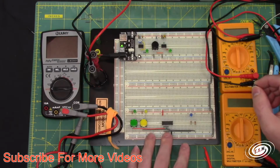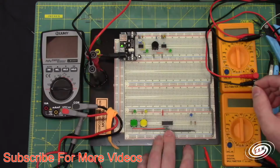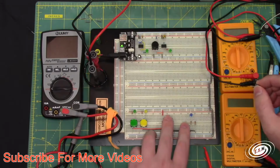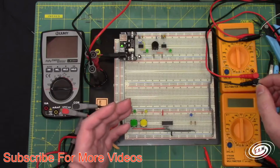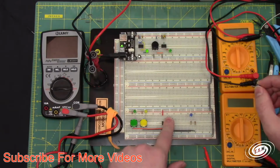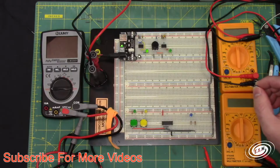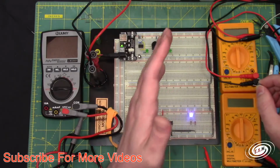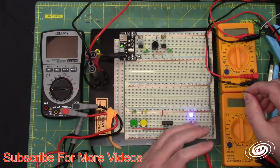And imagine if you had 8 of these hooked up, 4 chips. You'll get 2 out of each chip because they're NOR gates. You can get SR latch chips that have 4 on it, but you could have 2 latches per chip, and you had 2 chips. You could have 4 bits of data, and then you could plug in numbers and do different things with those numbers if you wanted to make something out of simple logic.